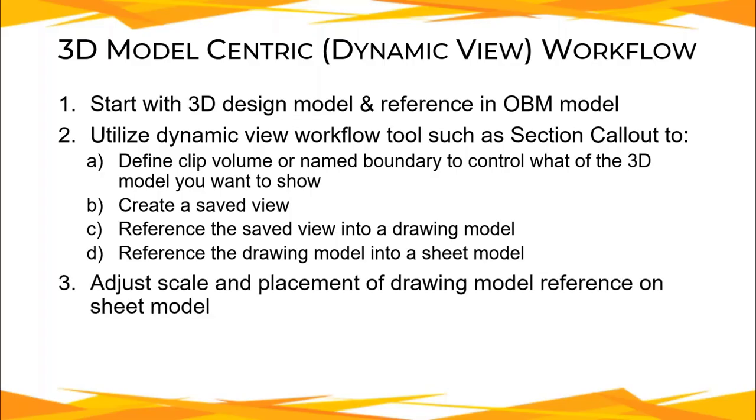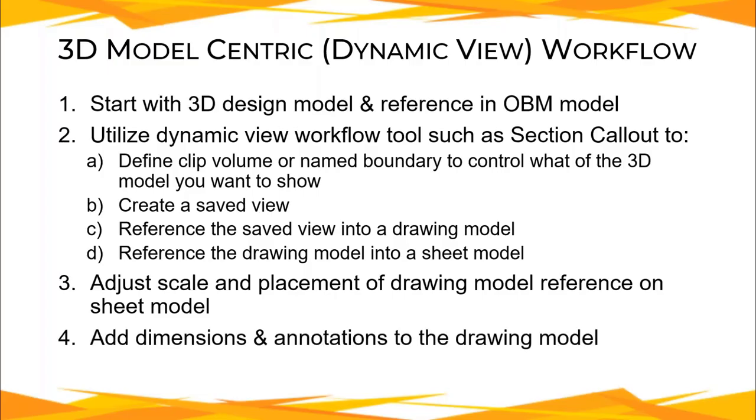And then seeing how that reference scale, like when you reference that drawing model onto the sheet model, you might need to change the scale to make it bigger or smaller and see how it fits on the sheet. So you're going to be adjusting that scale and placement of the drawing model on the sheet model itself. And then once you know what the proper scale is you want for that drawing model that's referenced on your sheet model, then you can go back to your drawing model and make sure that the annotation scale in there matches what your reference scale is in your sheet model. And you can add your dimensions and your annotations to the drawing model.